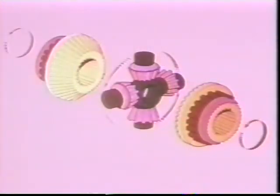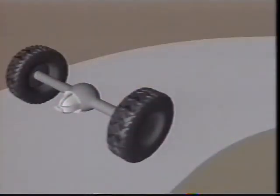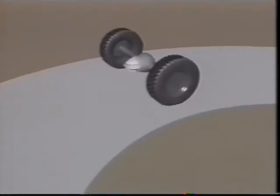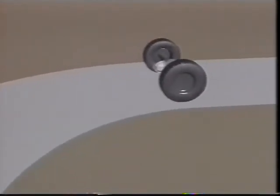When both wheels have equal traction and the vehicle travels in a straight line, the entire differential assembly turns as a unit. The clutch packs simply ride between the side gear and case half with no effect. But when the vehicle goes into a turn and both wheels have equal traction, the inside wheel slows down while the outside wheel speeds up.